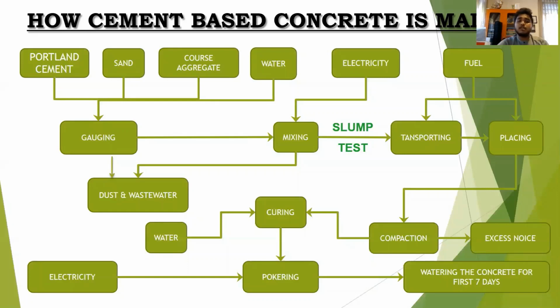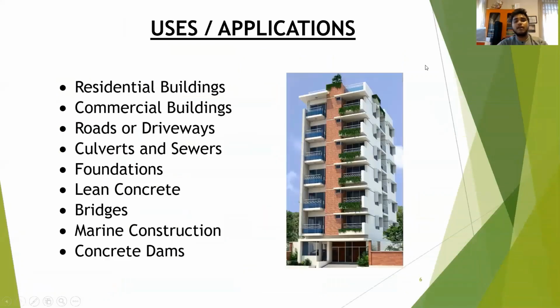Once it is placed and compacted, the concrete must be cured before it is finished to make sure that it doesn't dry too quickly. And finally, we have to pour the concrete and water the concrete for the first 7 days. And the next slide is about the uses and applications of concrete.